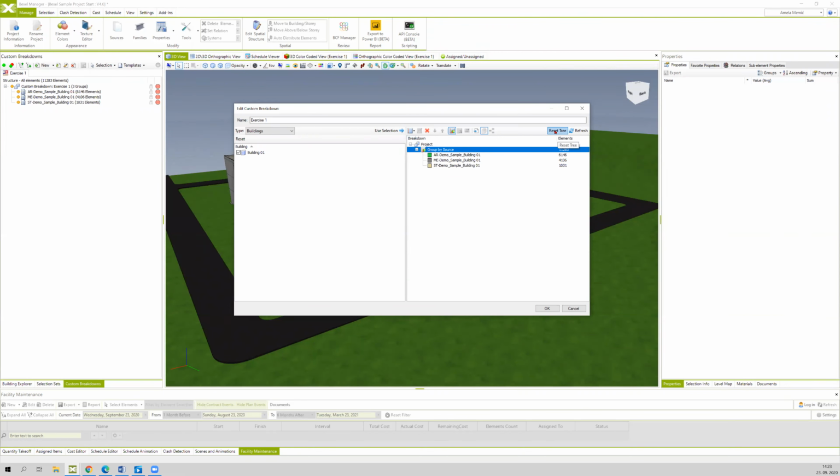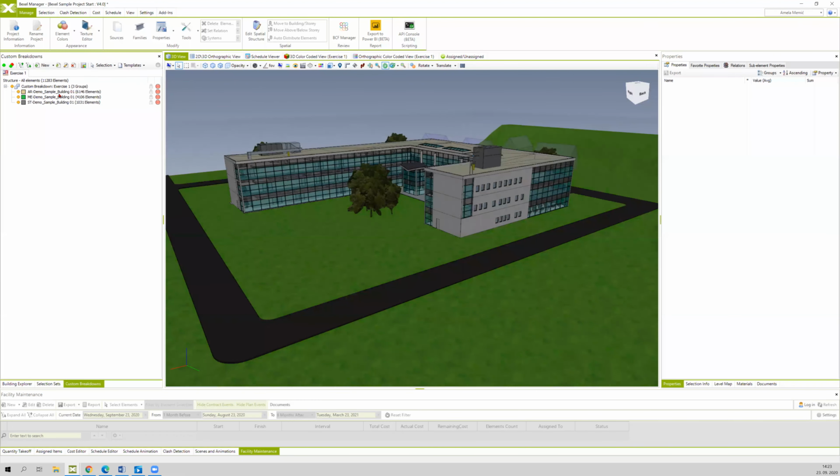So if you use the reset tree, you can see that now only the rule is visible and not the results. So click on it, and as you have added the color coding rule, we will finish the process by clicking on the OK button. And now you can see in the custom breakdown palette that every group, every source, has its own color.